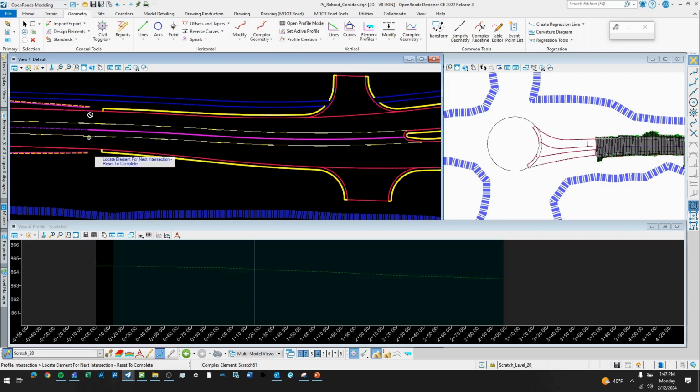For existing, if you're tying into that roundabout, I like to take maybe 10 feet and see what that slope is. And then I will tie in right to the existing ground and then continue that slope, whatever I get from that 10 feet back. That way there isn't a big bump or anything in there. You can change the slope later on with vertical curves and stuff like that. But for this one, I'm just going to tie right into this.